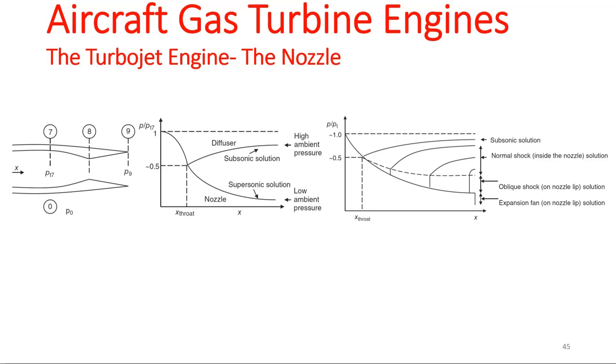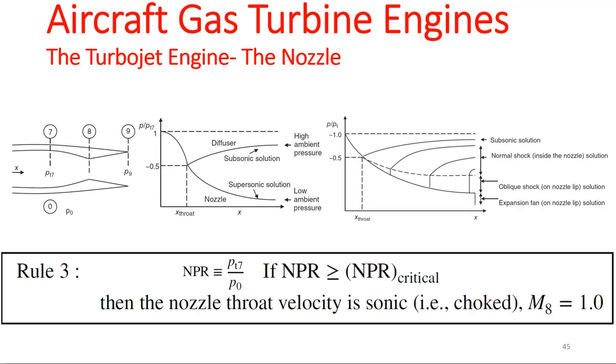Look at this figure, right? This figure goes from 0. That's a different one. They give you the same value when you have the choking, right? But this pressure here is the pressure at the throat, right? NPR is the comparison between the inlet pressure and the ambient pressure. Okay, let's go back. I actually have it here. So this is P naught, right? But this pressure here is P of x. That's why you see it's changing. The ambient pressure shouldn't change with x inside the nozzle, right?